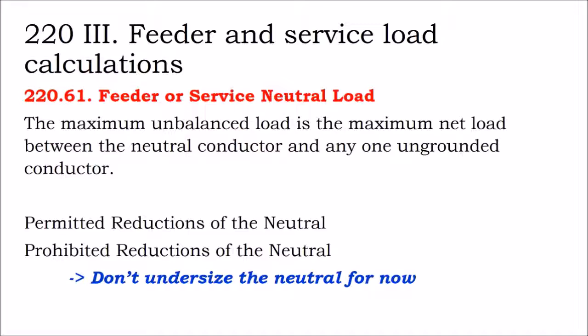the neutral needs to be the same size as the ungrounded conductors, your leg 1, sometimes leg 2 or leg 3 of power. And then beyond that, they say, well, under certain conditions you can reduce the neutral, and under other conditions you can't. So as a starting point with your design work, if you don't want to make any mistake, don't undersize the neutral, and then you'll be in the clear.